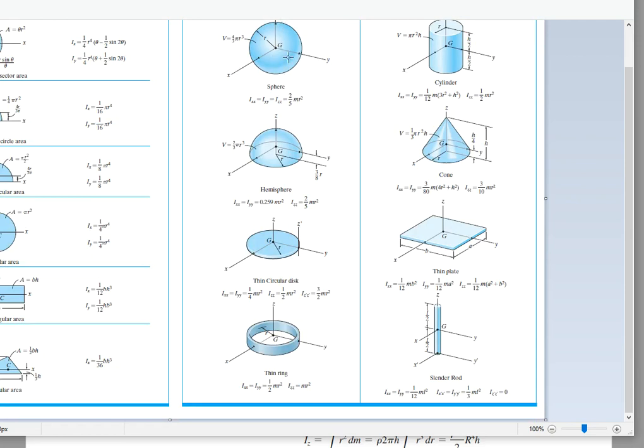So these will be what are called principal axes. They are through the center of mass and are axes of symmetry for the body. Since volume integrals can be split between partial volumes, we can calculate mass moment of inertia of composite bodies by working with the simple bodies that form them.